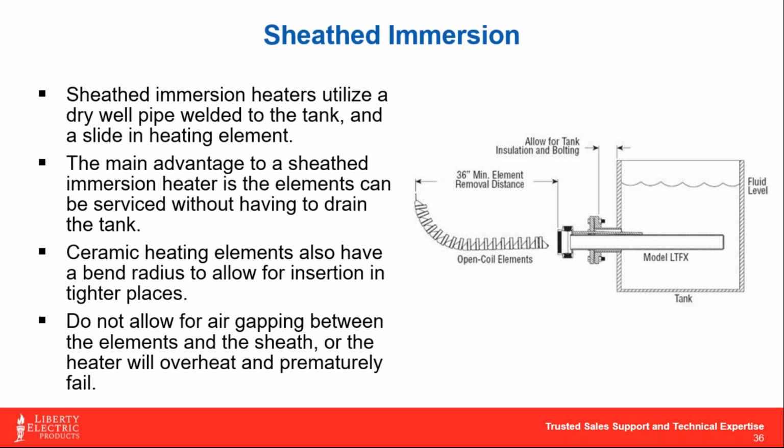A lot goes into having to bring another tank or some sort of portable reservoir on site to make that happen. So this can become a very, very convenient cost of ownership type of product where you can very easily insert heaters into that protective sheath and rewire them within a half hour and be up and running versus taking literally a couple days to drain a tank, change the heater, refill it, and go through that process.